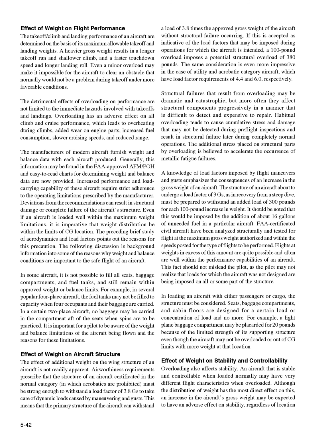The same consideration is even more impressive in the case of utility and acrobatic category aircraft, which have load factor requirements of 4.4 and 6.0, respectively. Structural failures that result from overloading may be dramatic and catastrophic, but more often they affect structural components progressively in a manner that is difficult to detect and expensive to repair. Habitual overloading tends to cause cumulative stress and damage that may not be detected during pre-flight inspections, and result in structural failure later during completely normal operations. The additional stress placed on structural parts by overloading is believed to accelerate the occurrence of metallic fatigue failures.